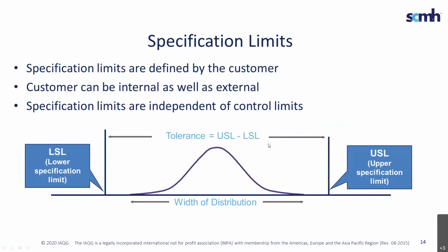All right, so when we talk about process capability, what we're really talking about is understanding what the process is doing when we compare it to the voice of the process versus the voice of the customer. The actual voice of the process is when we talk about the process and what it's actually doing, the measurements we're getting, the variation that we're seeing, and we compare that against what our customer wants to see. In other words, a feature or a pass-fail goodness, or is it functioning well? We compare what we're getting out of our process against that, and then we can actually report what we call a process capability.